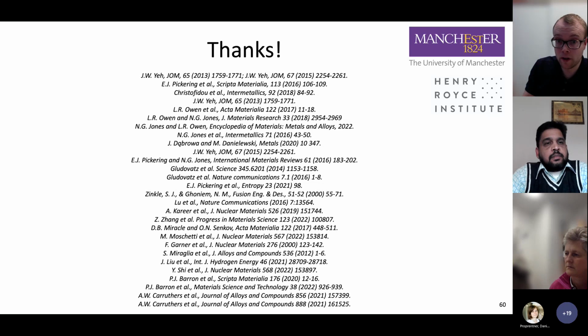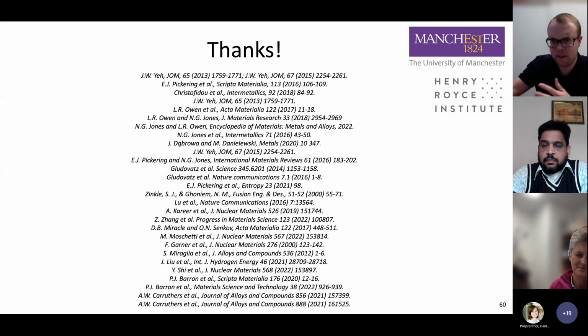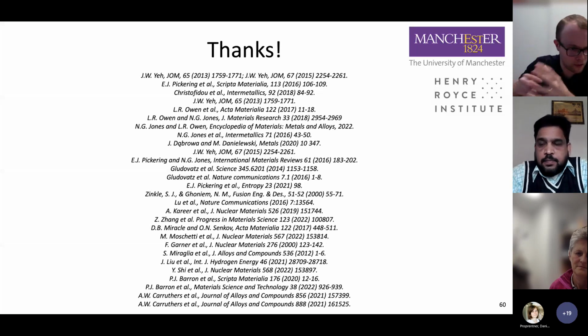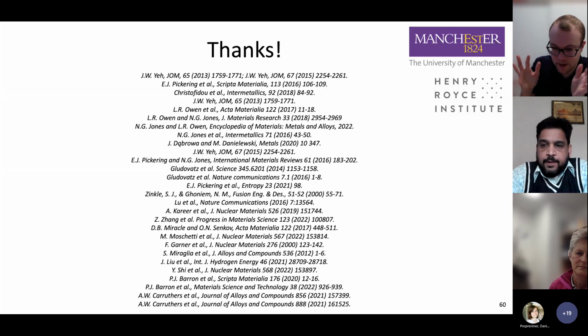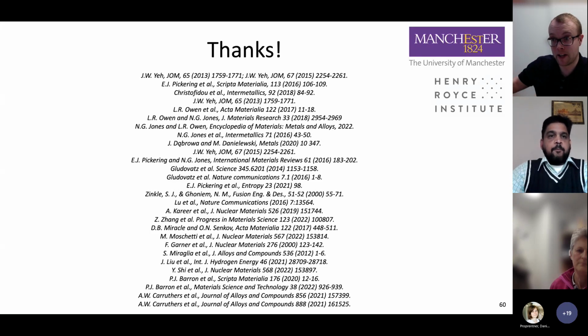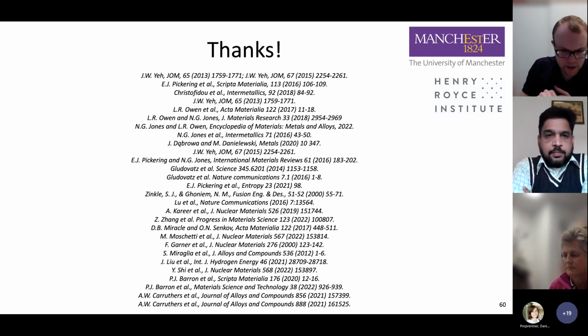And I think that's only a good thing if we're looking at developing really exotic, high temperature, high strength power plant concentrated steels, for instance. If we're going to introduce all sorts of crazy precipitates and alloy them a lot, or maybe introduce some new TWIP steels, I think it's only a good thing that the thermodynamic databases are being more rigorously tested by the high-entropy alloy community, and that has been fed through into steels. So that's the first thing.